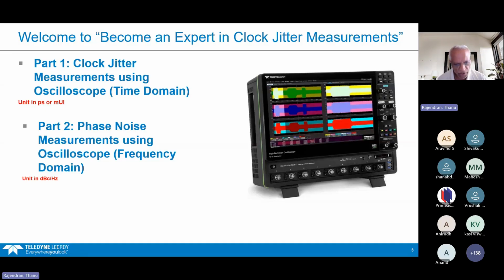If you take an edge, the edge determines when an opcode has to be fetched from the memory. Once the opcode is fetched, the next step is to decode the opcode. Third is to execute the opcode. So in 3 edges, the entire operation happens. That's the reason why the edge or the clock becomes very important for any analysis.